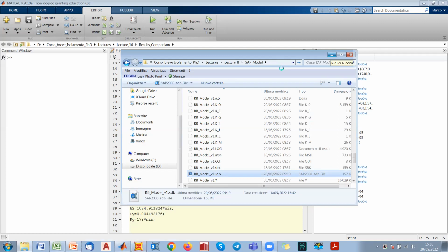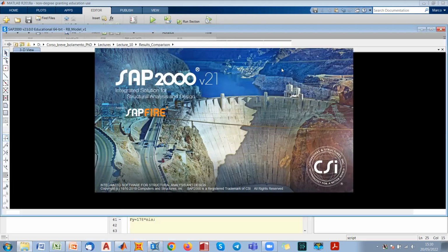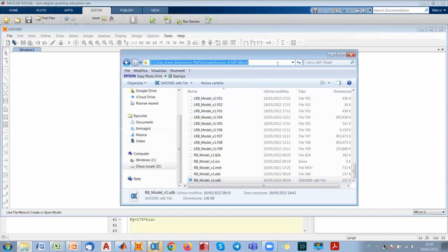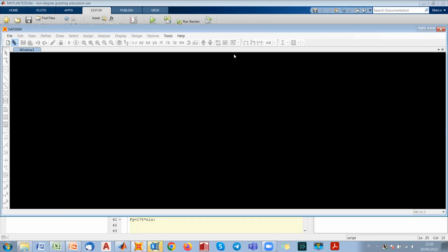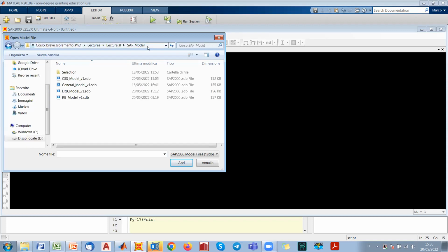But you see, what I wanted you to see with these numerical laboratories is that it is actually possible for us to perform some easy computations with the single degree of freedom oscillators, which gives a fairly good estimation of the displacement and force demand of the isolation layer. And so we are able to check if the mechanical properties that we have designed are actually good for the displacement demand that we obtained.